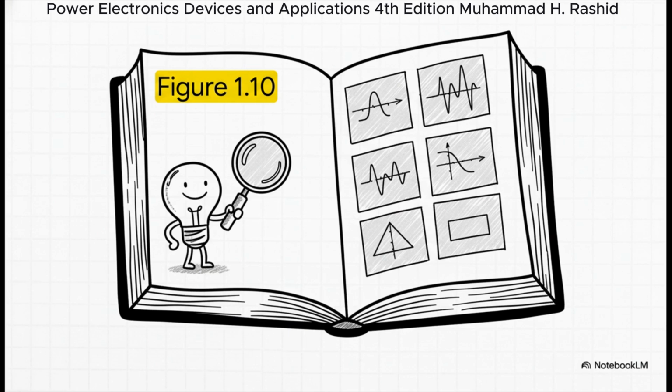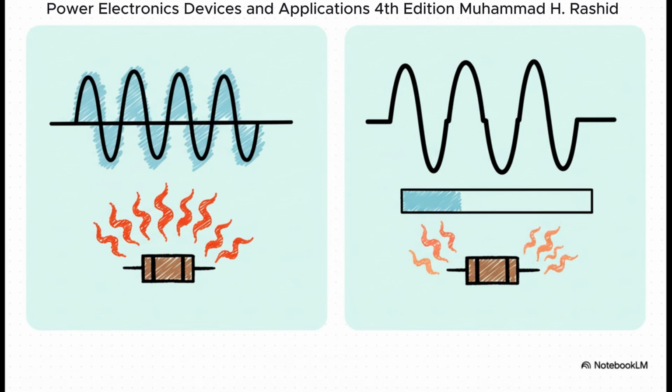Let's break down a couple of these to see how the shape really changes the energy it carries. Over on the left, that's the classic full-wave rectified sine wave. You've probably seen it 1,000 times. Its RMS value is just its peak divided by the square root of 2. Easy enough. But look to the right. This is what happens when you start pulsing that wave, turning it on and off. Notice that little K? That's the duty cycle, basically the fraction of time that the signal is on. See how it gets right inside that square root? This shows you perfectly that the less time the signal is on, the lower its RMS value, and the less heat it's going to produce.